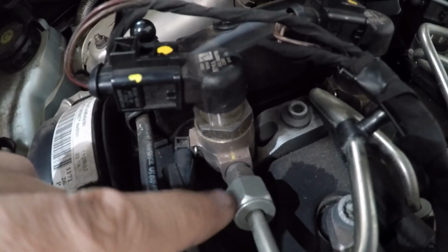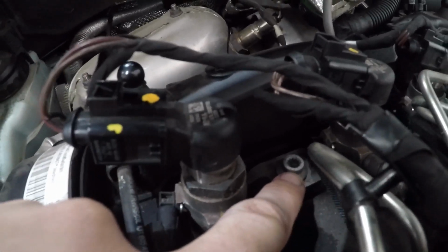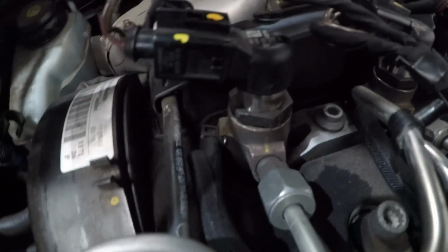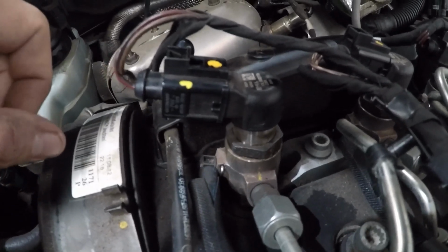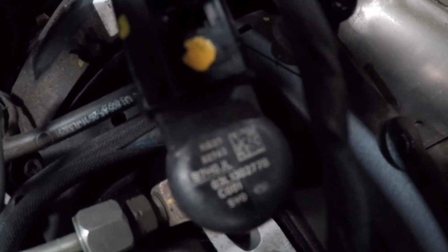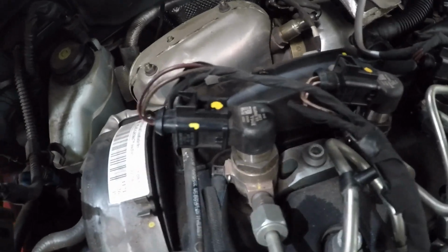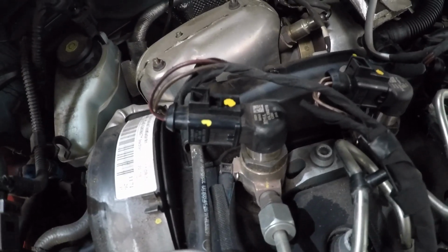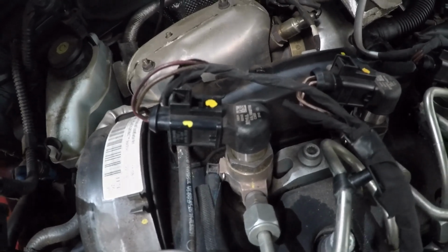We're going to undo this fuel line, obviously at this end and this end too, so we can get it out of the way. Once that's off, we'll remove this bolt here, take off this bracket that holds it down, and then we can take that injector out. Hopefully it'll come out easy enough. When we get the new one, we will make note of the numbers on here. I don't know if you're going to be able to see that very well, but that is the numbers that we're going to need to code this injector in with VCDS. So I'll get that swapped over for you, and then once the new one's in, we'll get those numbers and we'll jump on the VCDS and I'll show you how it's coded.